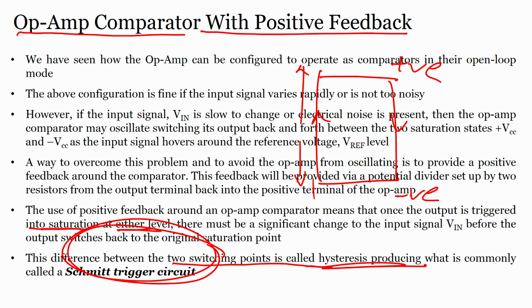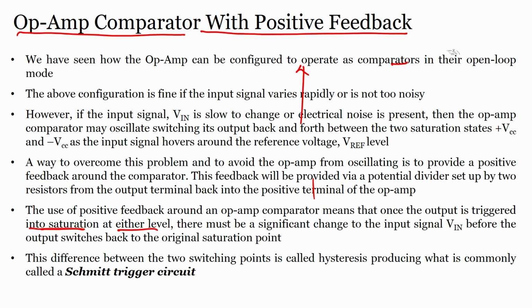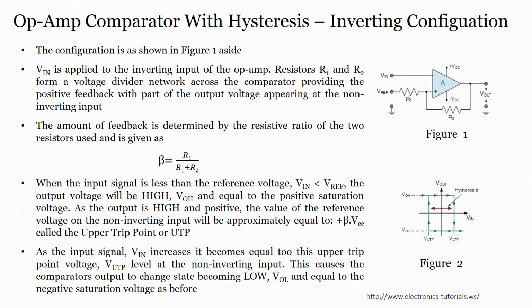Alright. So, if somebody asks you what is the difference between multivibrator and Schmitt trigger, it is the same thing. Yes, how we can design the multivibrator, you can always say that we can apply positive feedback to the comparator using the potential divider. Alright. So, it is easy, so do not worry about it, right.